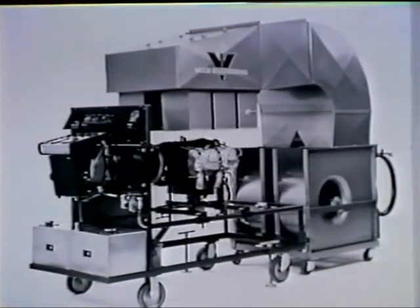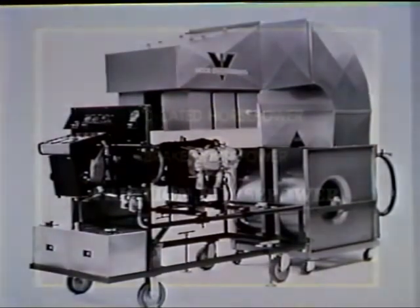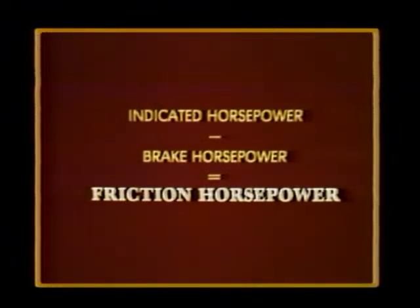Another engine test is made on a dynamometer. This equipment measures the brake horsepower, or the power actually being delivered to the propeller. This brake horsepower is always less than indicated horsepower by a factor called friction horsepower. This is the power that is used to turn the engine and compress the fuel-air charge.